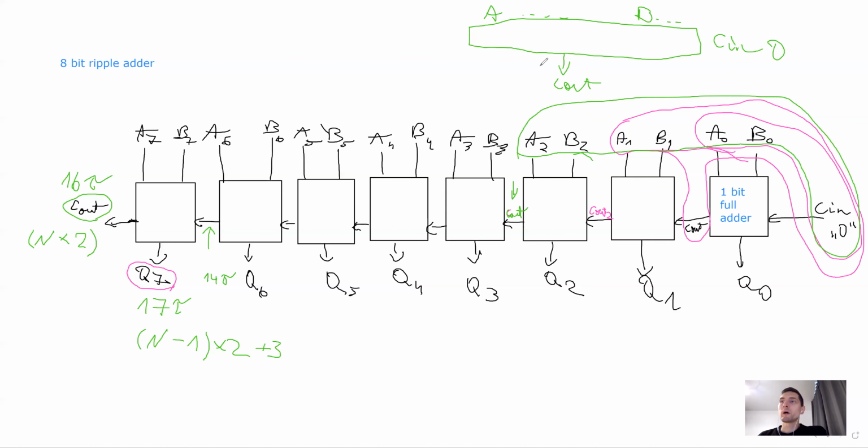And there's also a simplified method called carry propagation or something like that, which produces almost as good results, but with a little less work, because in this case we would have to write a truth table for each carry, and each truth table, since we have, for example, 64 inputs, how many combinations would it be? 2 to the power of 64, an enormous number of combinations. So mathematicians have figured out a little bit simpler way to calculate it. So generally, in modern processors, we use something called a Carry Lookahead Unit. Okay, I'll write it here.